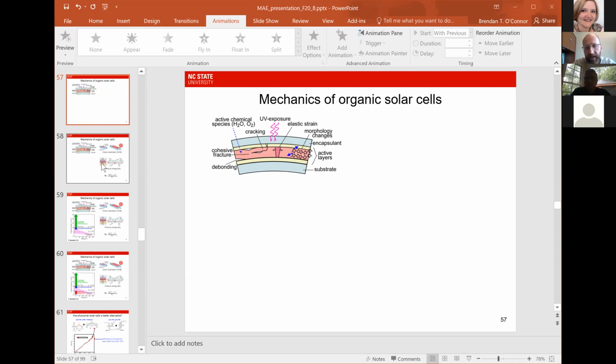So tandem solar cells commercially are typically these really expensive gallium arsenide solar cells that are used for space applications, and they have like 40% efficiency. And you could apply similar concepts here, stack them to try to improve efficiency, try to improve the spectral absorption range. But when you do that, you usually have a loss in voltage. But if you make tandems, you can improve the spectral range without the loss in voltage. And so people are actively looking at that, including Frankie So in the Material Science Department here. But yeah, it would probably reduce the transparency for sure.